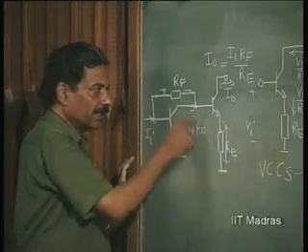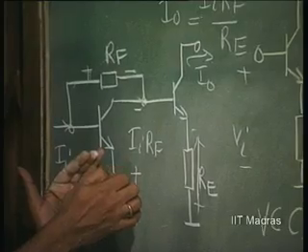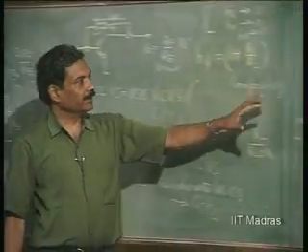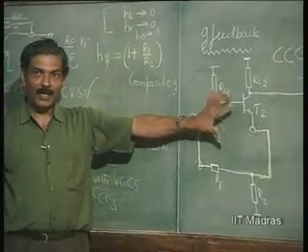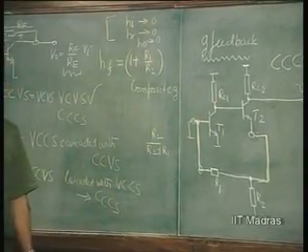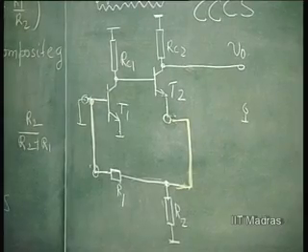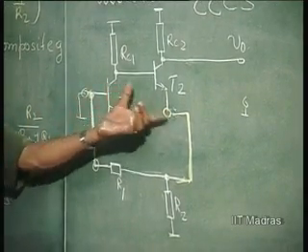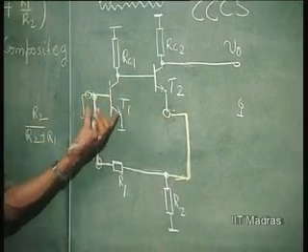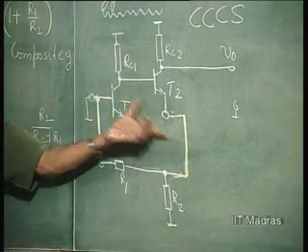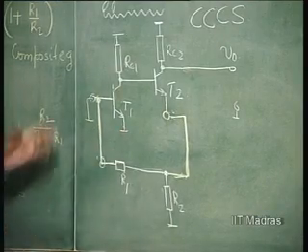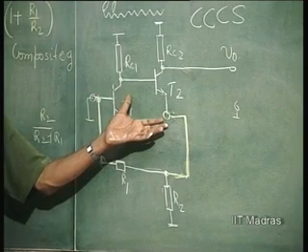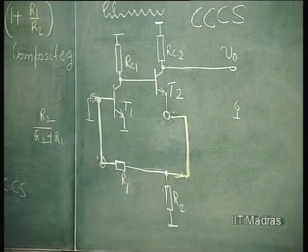Two local feedback structures are coupled together, right. So, that is the difference between this structure and this structure. This local feedback and overall feedback have their own advantages and disadvantages. Obviously, the first advantage here, which is very clear, is that since you are cascading two amplifiers, the loop gain is always going to increase, right, compared to one amplifier. So, the loop gain of more number of stages will always be higher than the loop gain of less number of stages, that is obvious.